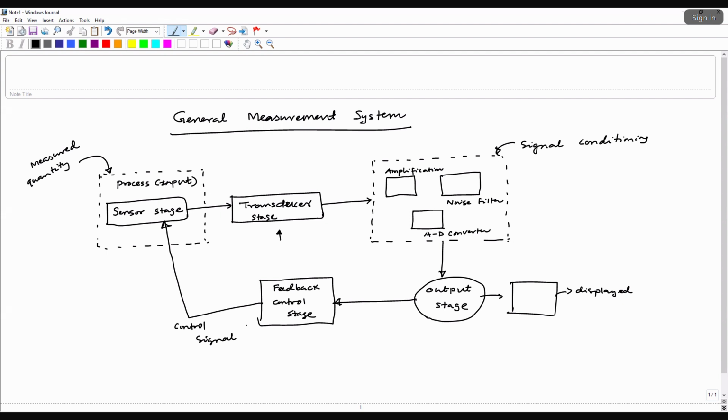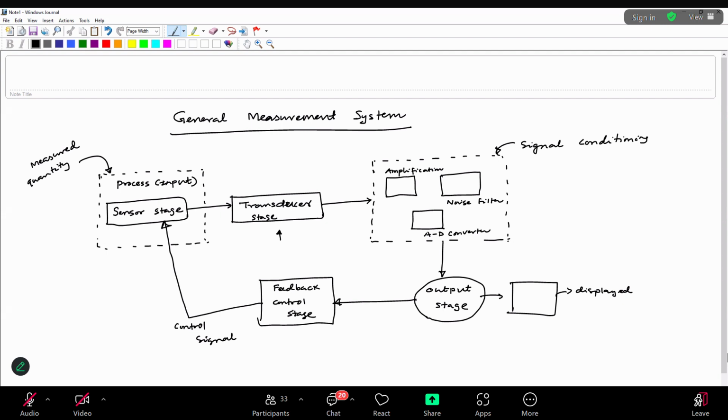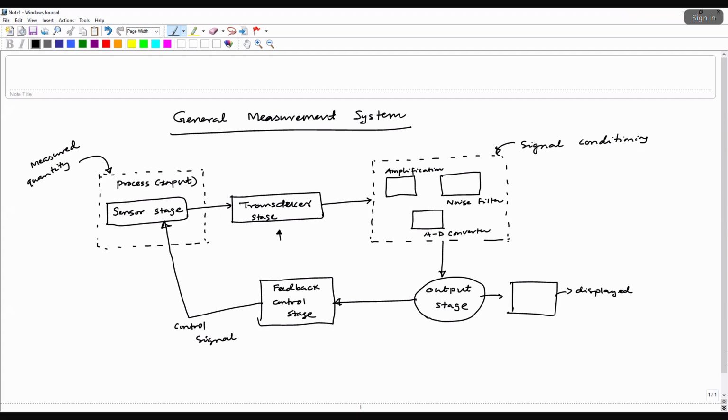For example, let's say you are measuring temperature inside an oven, right? And you have set the temperature of the oven to be 80 degrees centigrade. So the sensor basically reads the initial temperature inside the oven. Let's say it's ambient. Then it signals the heater for doing the electrical heating, and the temperature slowly rises from 25 degrees centigrade to 30 degrees, 70 degrees.